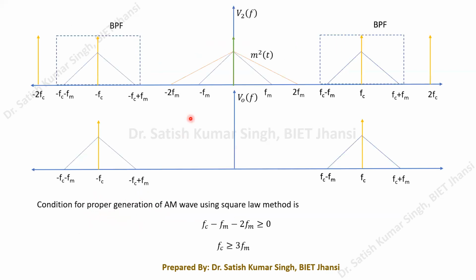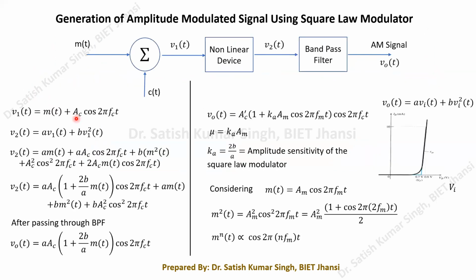So all the DC terms will be added together and give one particular impulse at frequency f equals 0. So at this point we get the addition of several DC terms. And now we get one impulse at f equals 2fc, and similarly another impulse at f equals -2fc.